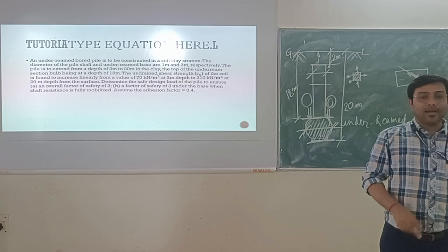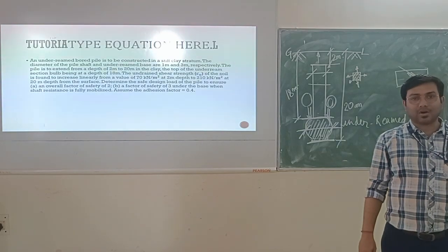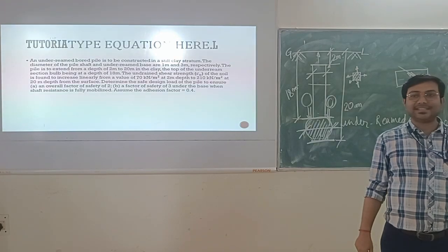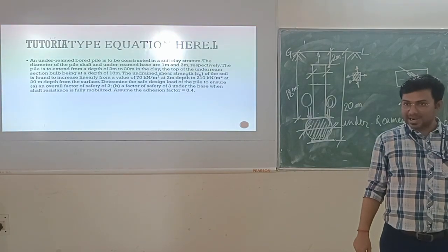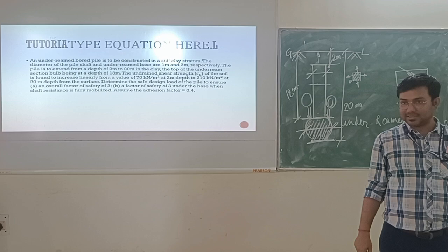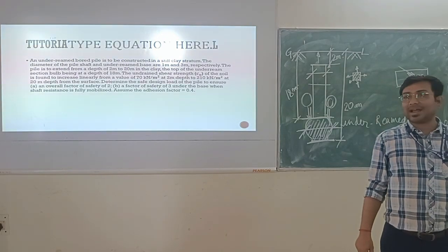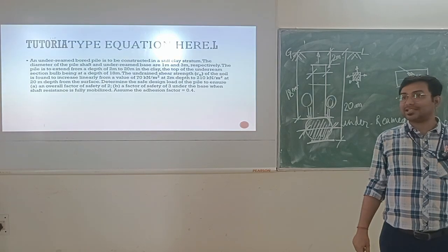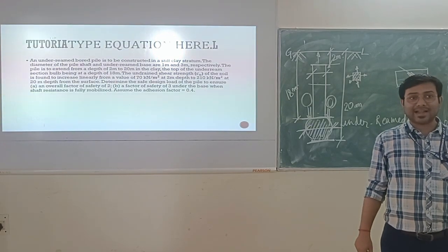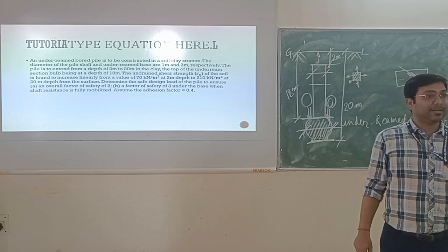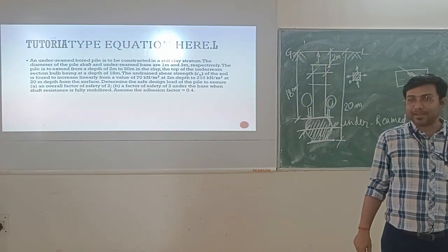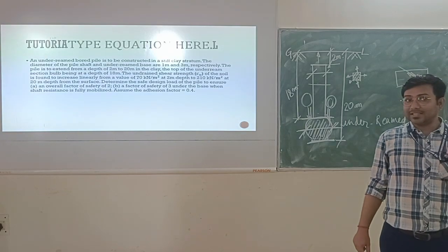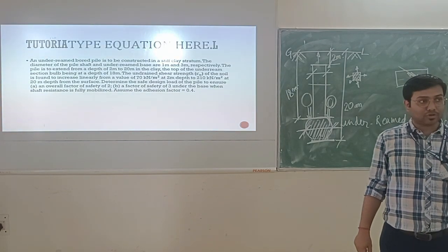If the soil particles are granular, larger particles, then pore size is larger. We have studied this in the basics of soil mechanics. Larger particles mean larger pores also. In sand, larger particles, larger pores. That means in that kind of sandy soil, drainage may happen, drained condition may occur. But in clay soil, smaller particles, smaller pores.